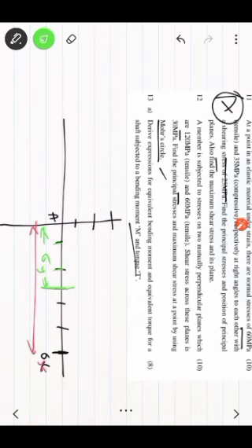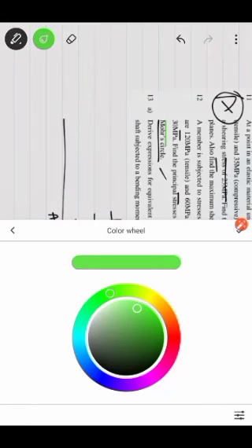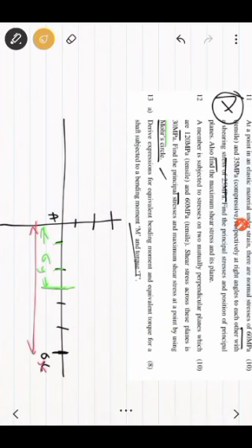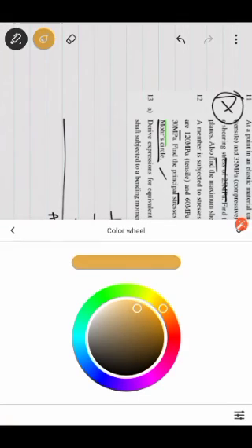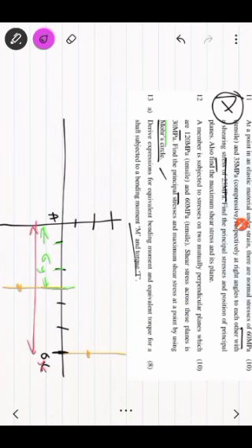Now you draw tau. This is tension side. Compression means you have to do it in the reverse direction. So this is tau xy. You draw tau xy from sigma x and sigma y. So sigma x, sigma y, what is the value? It is 30, so it is 30 here and 20 is here. Join these two lines, it will meet here. Using this as radius, draw a circle.